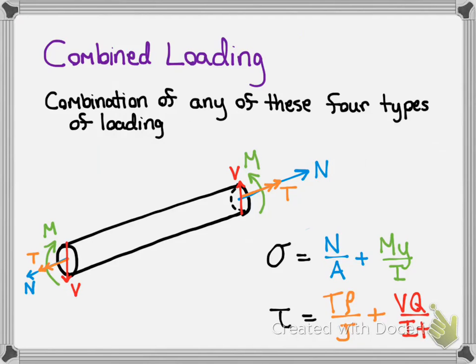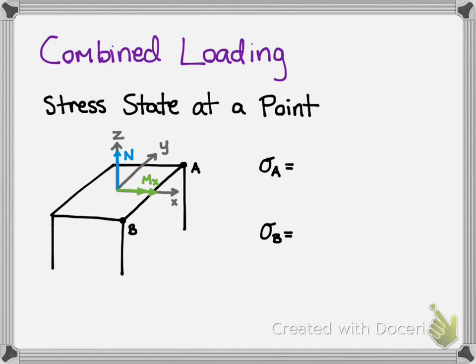Those are the two fundamental equations of combined loading, and that's just about the basis of what you need to know. In many cases, in most cases actually, it's not quite as simple as simply adding the two types of stress together for normal and shear, because sign matters.